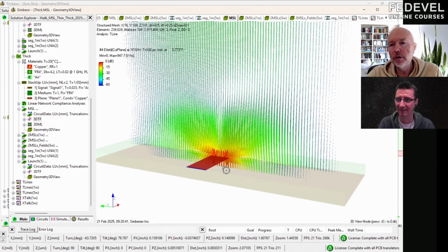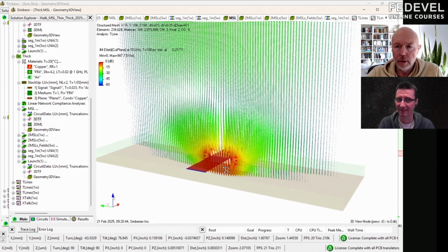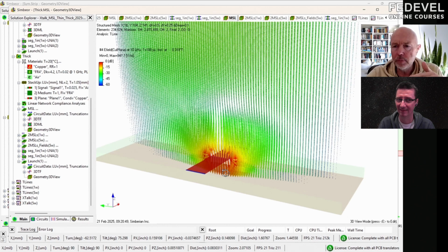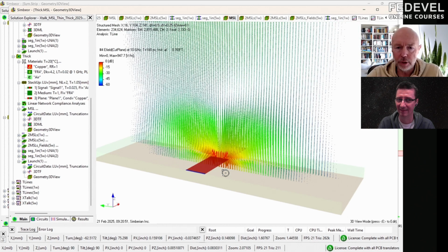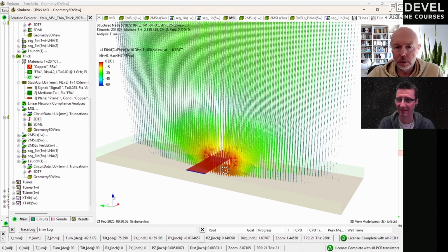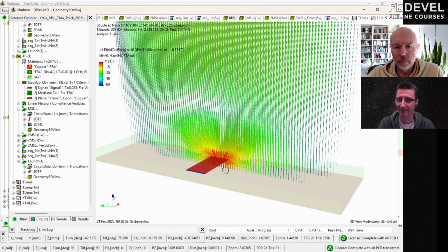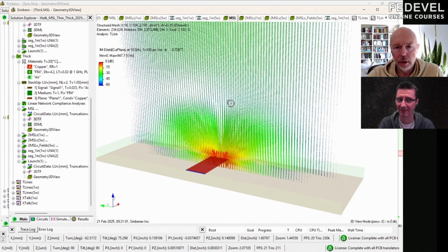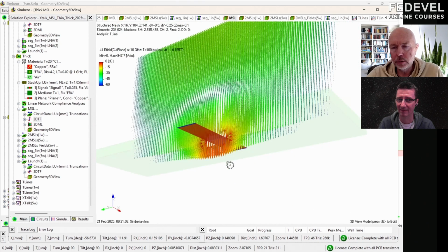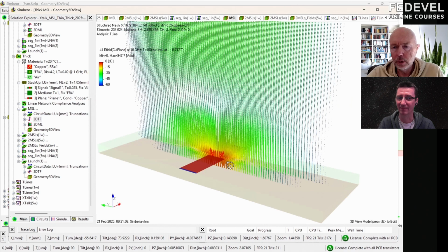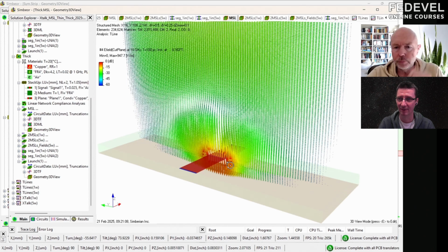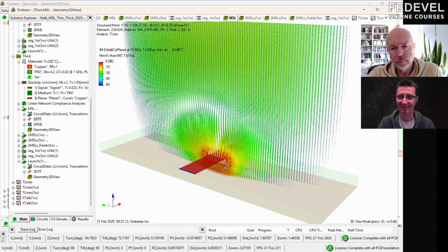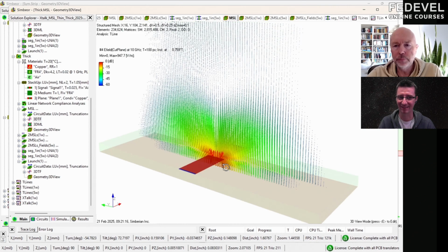This is the main disadvantage, I would say. This high dispersion of the characteristic impedance, the change of characteristic impedance with the frequency. Plus, if you get high order harmonics in your signal close to 10 gigahertz or above 10 gigahertz, they're going to radiate and violate all the standards, especially with digital signals. So standard two-layer PCBs can't really be used for higher speed signals.